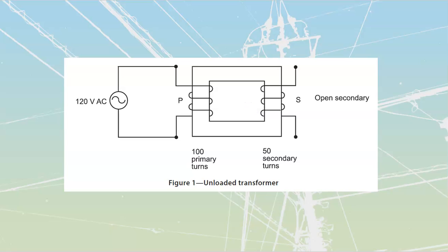What does an inductor do? It creates a counter EMF to oppose the main applied EMF. We use the analogy of a little linebacker and a big linebacker, right? It's going to create a counter EMF, which is going to be a reflection of itself, but just a little bit smaller. It always overpowers the counter EMF, but the counter EMF pushes back against it, slows it down, and that's what slows down the rate of electrons traveling from the source through this.